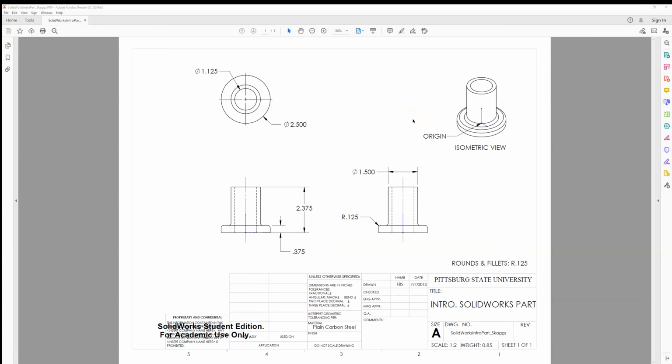One of the things we talked about is SolidWorks being parametric, and feature based as well. So one of the things we start doing is we look at this part and start breaking it down into individual features. The first feature I see is this base feature right here. It's like a circular disc component, and then on top of that circular disc I have this other circular piece as well, except it's much taller, right? I can use these dimensions here to say, from this surface here to this top surface it's about 2 inches. And then I've got another feature, I guess it'd be feature number 3.